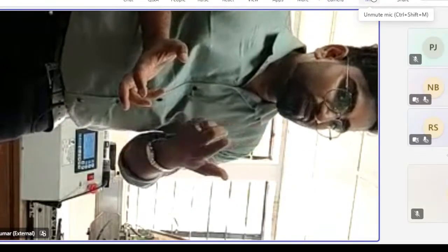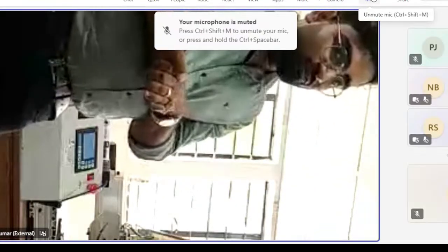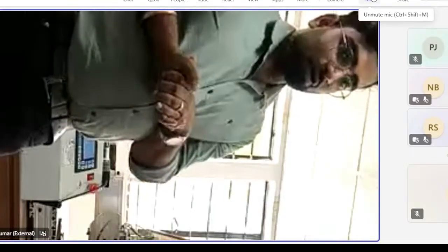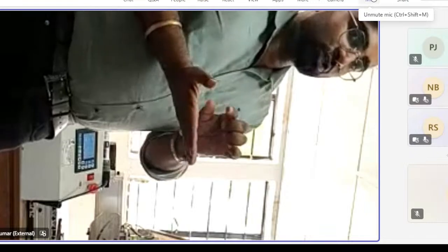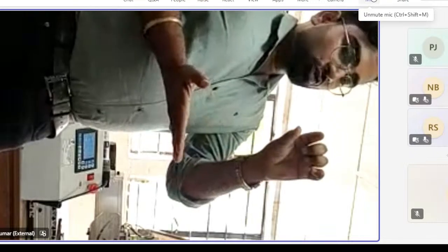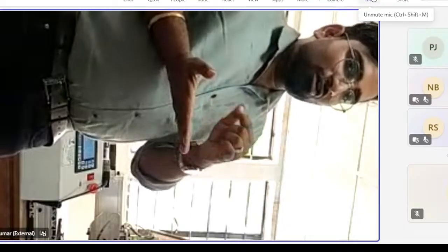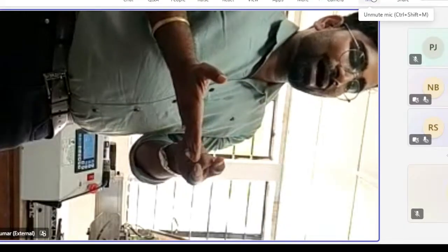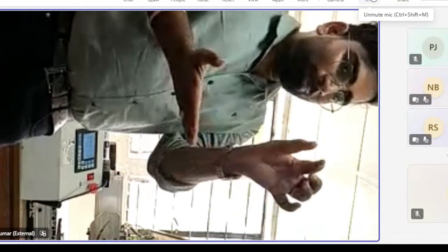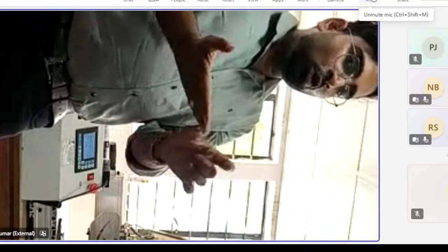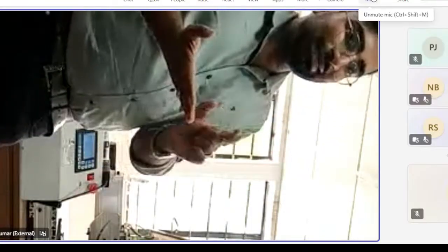What is the meaning of optimized data? Suppose we want to deposit a single wall material. What is our objective? Our objective is to create a 3D printed part. During the deposition, we want a higher reinforcement part. Higher reinforcement means lower penetration, which means a lower dilution percentage is needed.